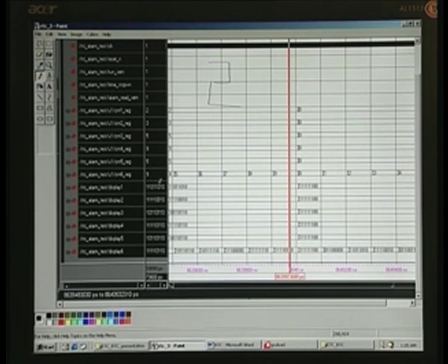So C and F are 0 here, and if it is 3, what you should have is A, B, C, D, and this is E and this is F. E and F must be 0, that is for A, B, C, D here, E and F, you can see this. This display 2 or counter 2 must have a 1-to-1 correspondence. This is a 7 segment display, and 1 lights up the LED, remember that. So 3 is also verified. Now let us go for 5.